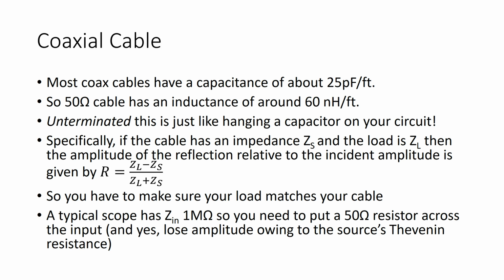So here's a formula that once again comes from electromagnetic theory that says that if your cable has an intrinsic impedance ZS, and the load on the end of the cable, which could be a resistor, remember the impedance of a transmission line is resistive, is ZL, then the amount of amplitude reflected back if you have a wave in the cable and a load ZL at the end of the cable is given by this formula here, (ZL minus ZS) over (ZL plus ZS).